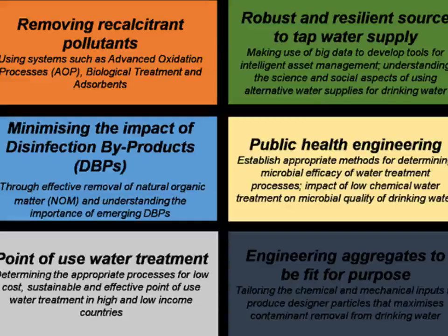The technique is also used to recover water for reuse. Similarly, 70% of the proteins and 80% of the lactose can be recovered from cheese whey by reverse osmosis, which otherwise would cause a serious pollution problem.